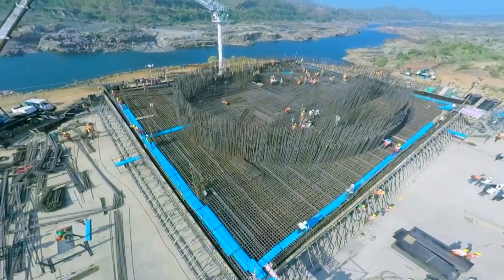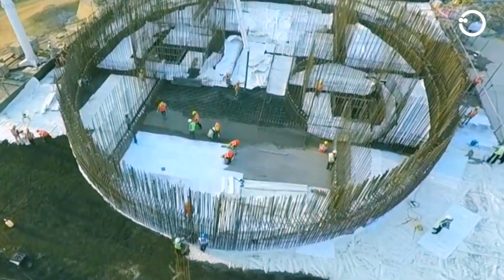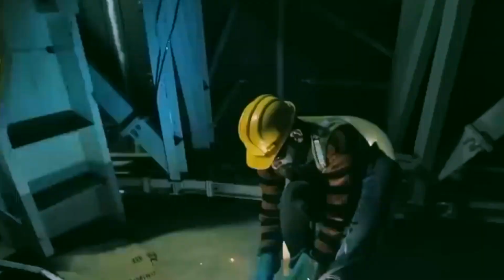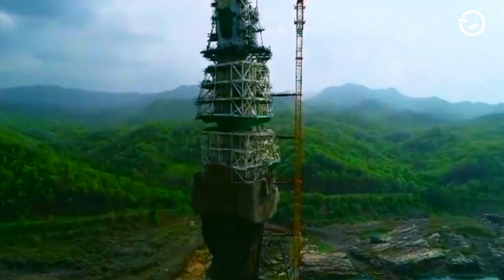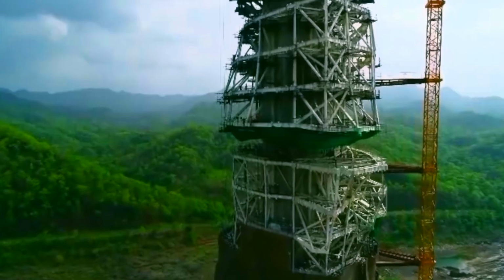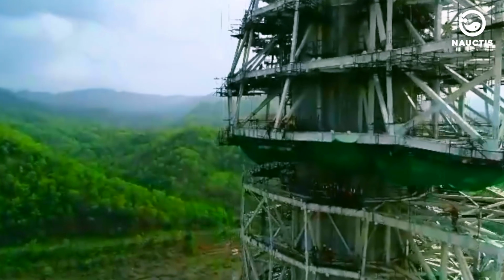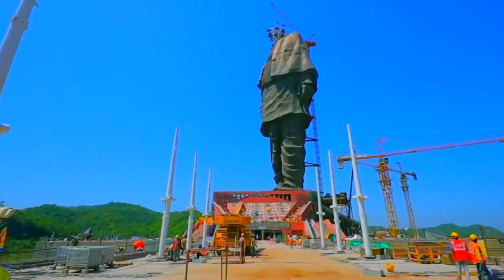Next, the structural steel grid frame was erected from the concrete core. For this, the W360 shaped steel was welded in the shop with internal steel shapes in the core. Internal steel work continued, followed by core casting. After that, bronze-clad panels were connected to the grid frame.